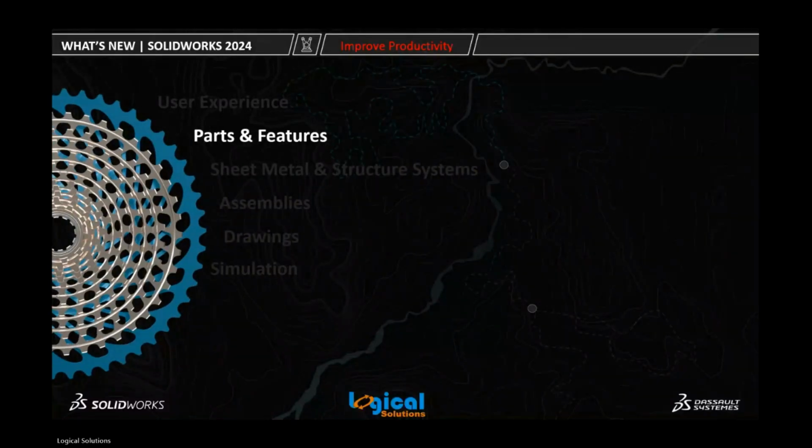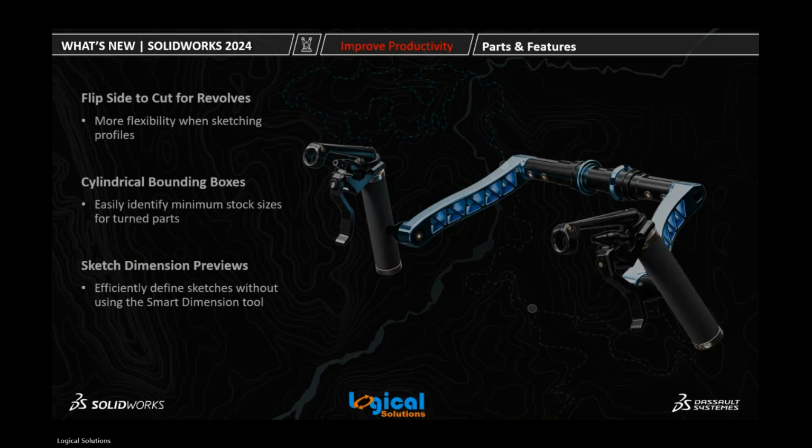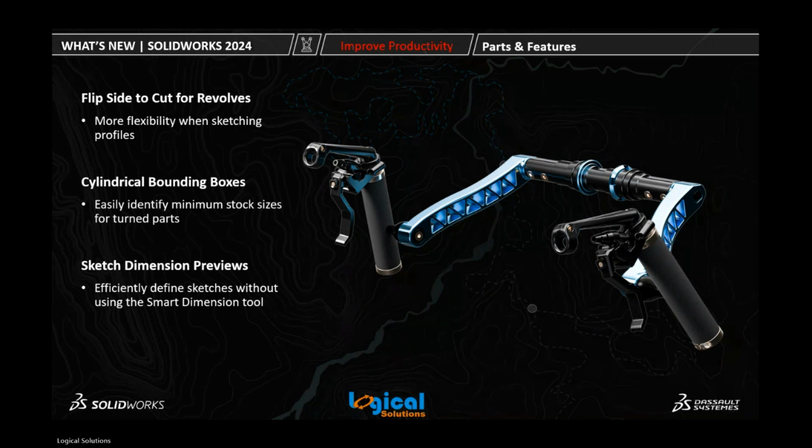And these are a few enhancements in user experience. And let us move a step forward and look at the enhancements in parts and features. And the first enhancement in parts and features is flip side to cut revolve. We can flip the side to cut revolve features similar to the cut extrude features. This retains the inner portion of the sketch and discards the region outside the sketch. In the earlier releases, this option does not exist and we required more steps to achieve the required results. Let us move on to SolidWorks and see how this option works.